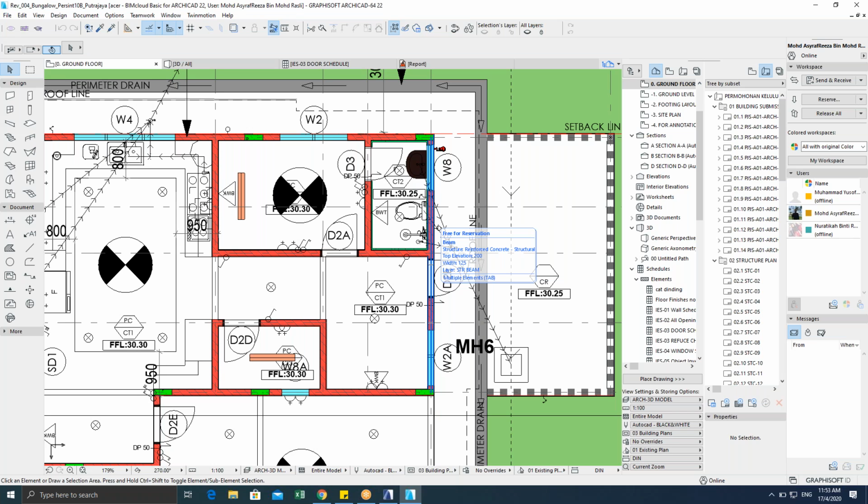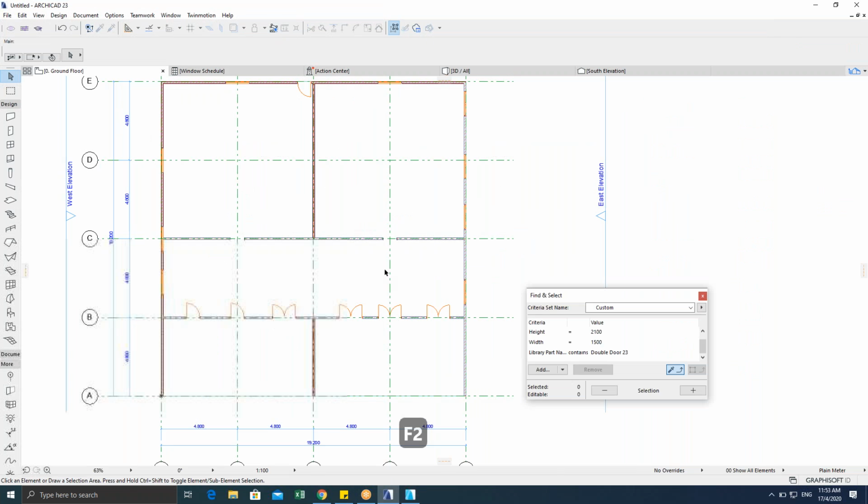Okay, I was typing, but maybe I can just say. The previews in the schedule are pretty much just an elevation of the model. And for schedules, you actually have settings similar to an elevation. So you can set the model view options, you can set graphic overrides, etc. Unfortunately, with the schedule, you don't see the quick options bar at the bottom, which you would normally see in a plan or an elevation, but these still apply.